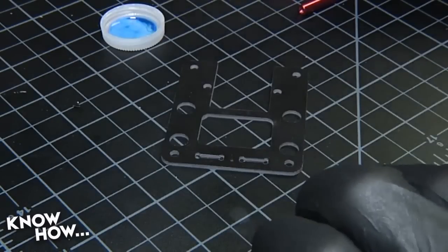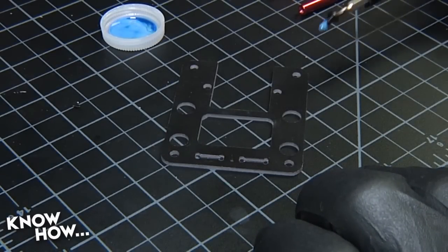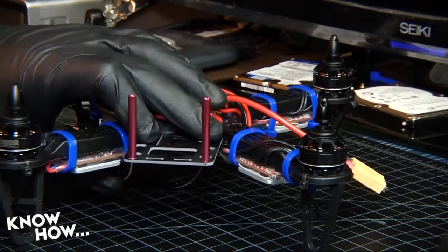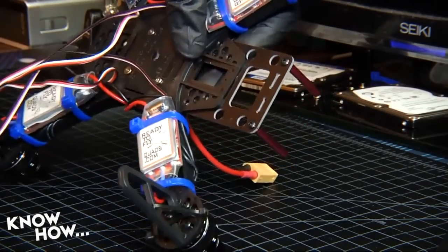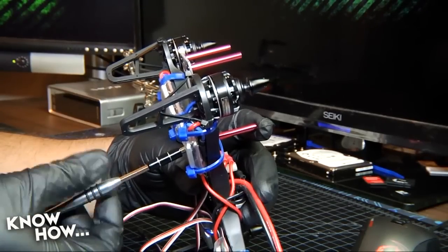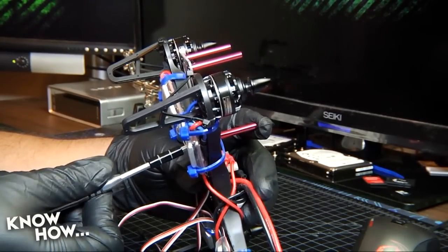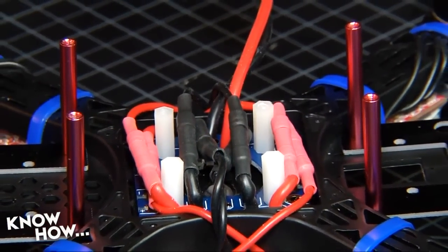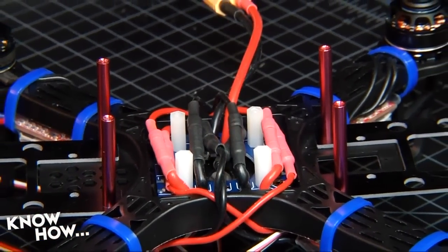Use a dab of Loctite glue to make sure that the screws don't vibrate free. Mount each of the small plates on the front and rear shelf of the frame, then fasten a screw through both the frame and the small plate to an aluminum standoff, once again using Loctite glue. You should now have a cage attached to your frame with 8 standoffs, but without the top plate.